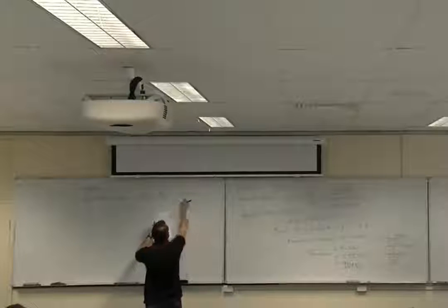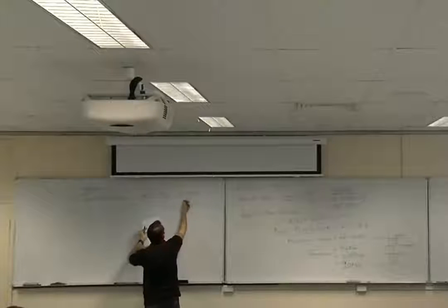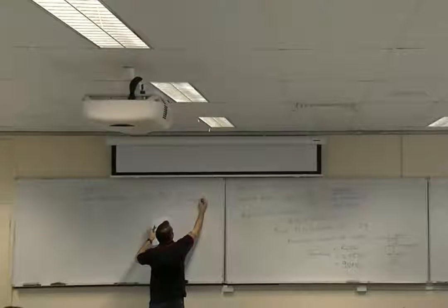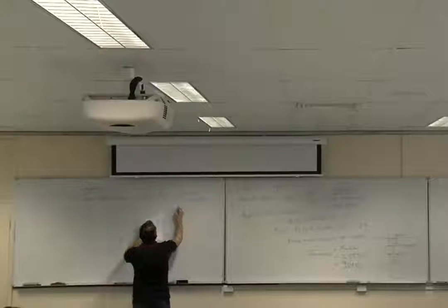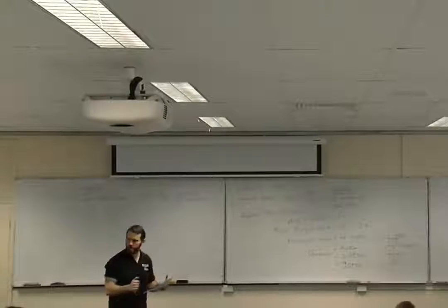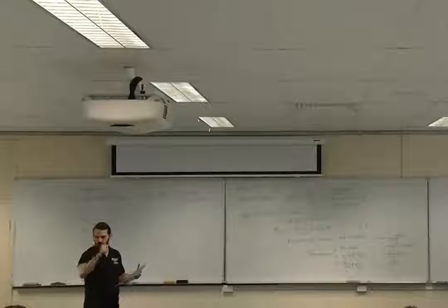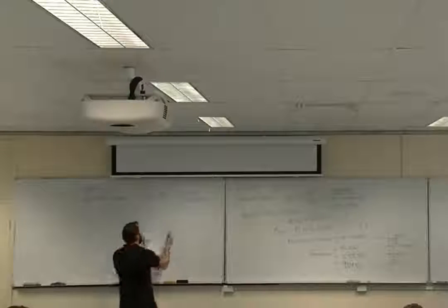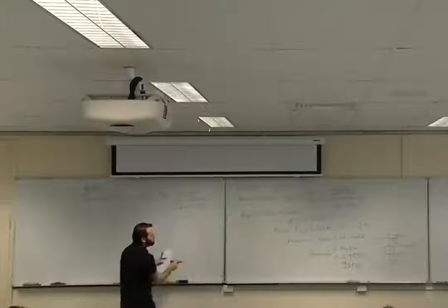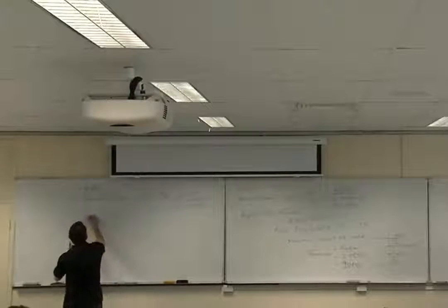And A in this case is the cross section minus the 2 notches, so 0.1 minus 0.03, times the depth, which is 0.025. What does everyone get for that? 25.7 MPa, great.